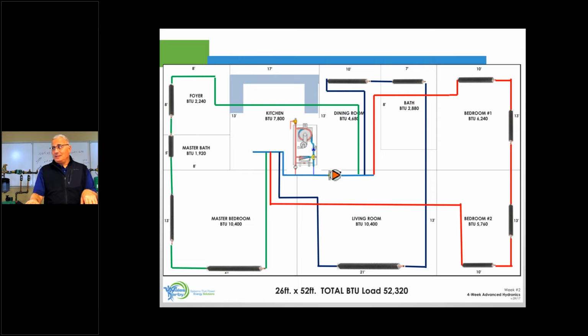Let me know if somebody's saying, like, write this on the board, and we'll do that. And if I do my best guesstimation as to the length of the loop, I came up with 84 feet. Okay? We'll address the head afterwards, but I just want to say that's how I got the total equivalent length of that loop at 84 feet.